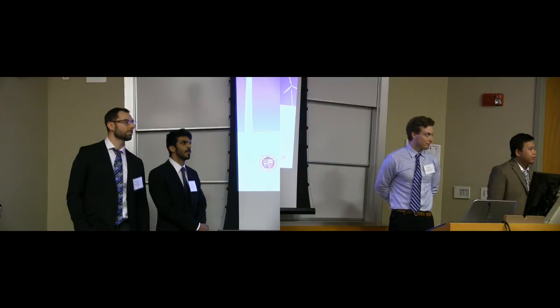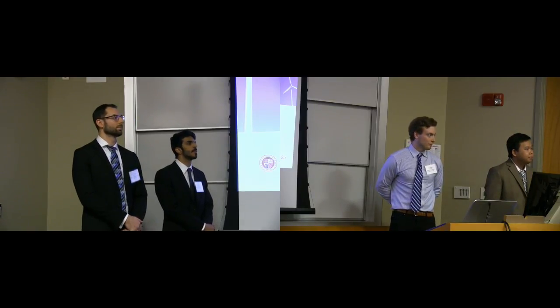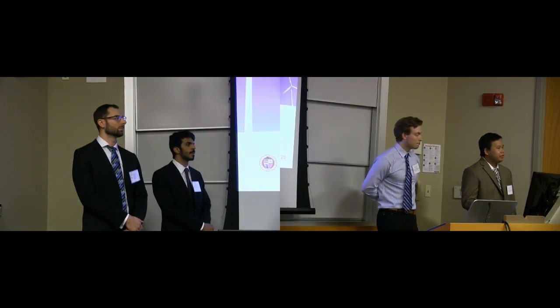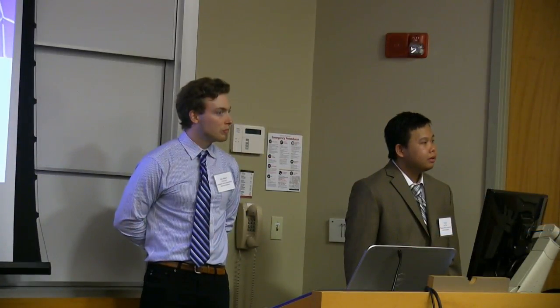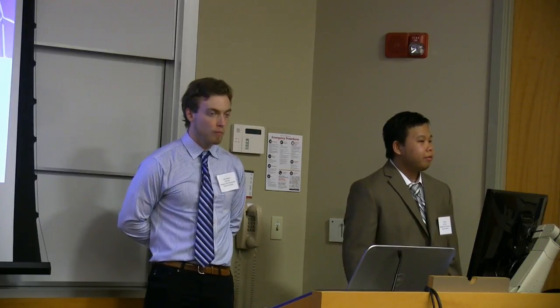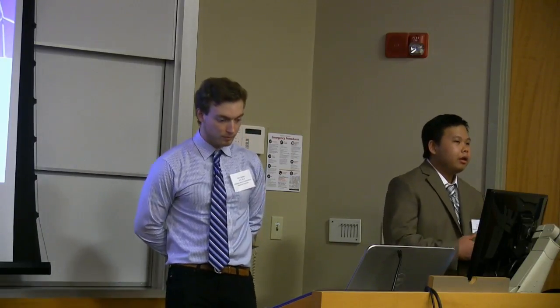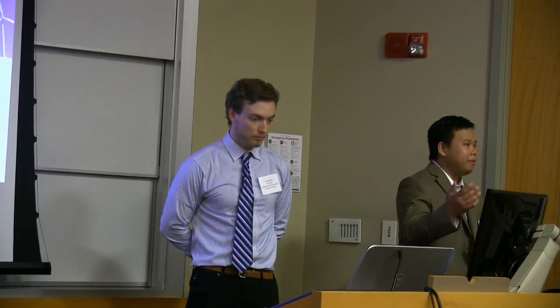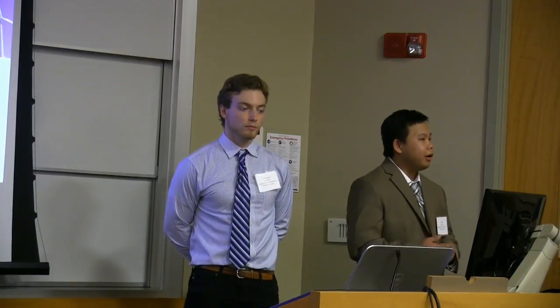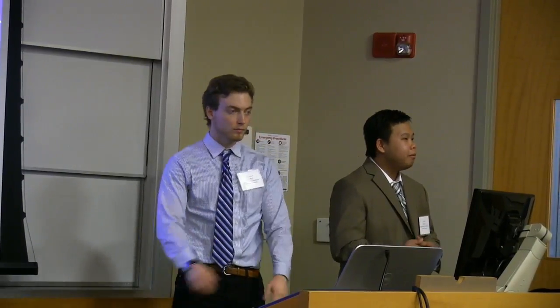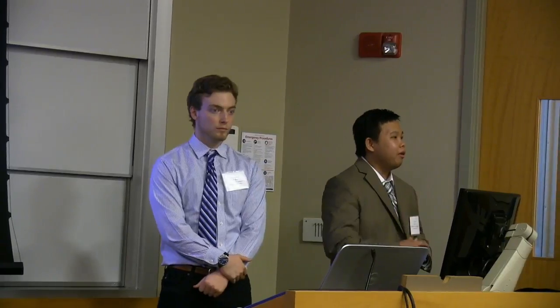Do you guys have any thoughts about redundant controls that might be necessary on the full-scale turbine for loss of load shutdown and stuff? I'm not familiar with the redundant control. No, I was just curious if that was something that might be required on a full-scale turbine, or if you had any. Oh yeah, for a full-scale turbine, most turbines have an active pitch as opposed to the fixed pitch that we did have, and they also have an active yaw. So they'd be controlling both the blade angle as well as the rotation of the turbine.